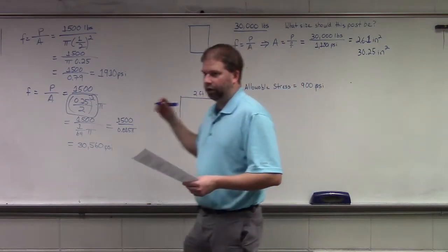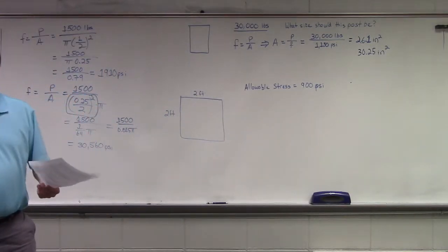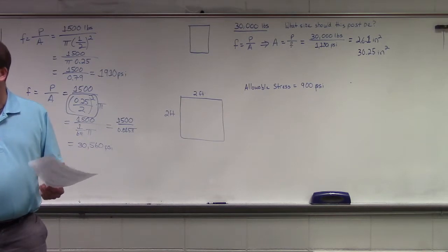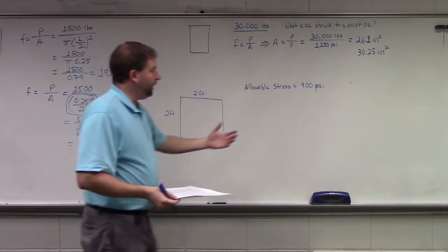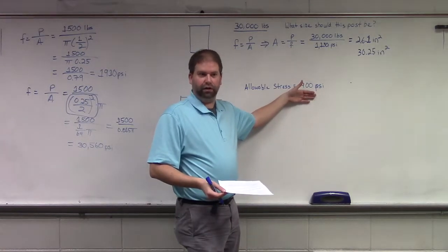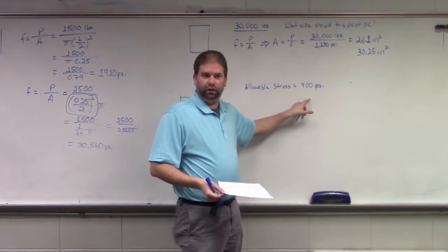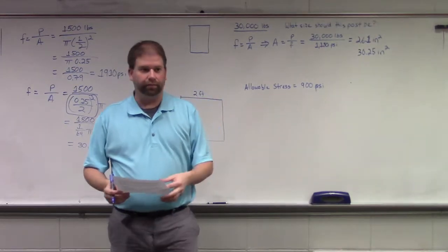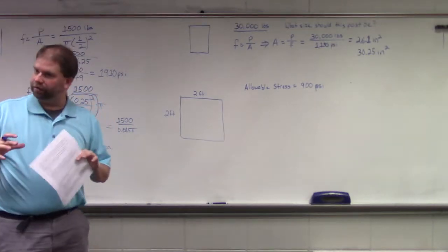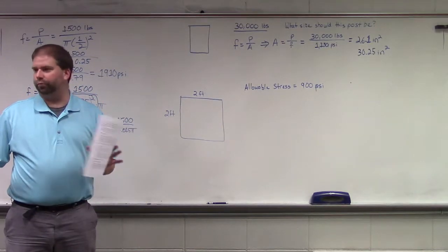For those of you familiar with concrete, does that seem like a low number for concrete? It should. The reason being, we want to make sure that we have sufficient capacity with our concrete. What happens if we start getting close to this stress in our concrete? It's going to start cracking, and as soon as our concrete starts cracking, we're going to open ourselves up to a world of problems.